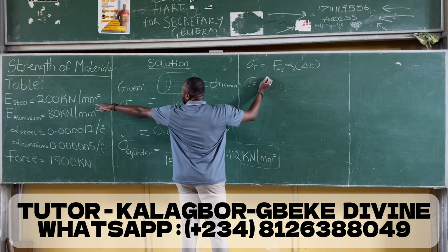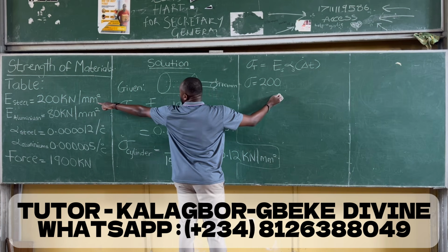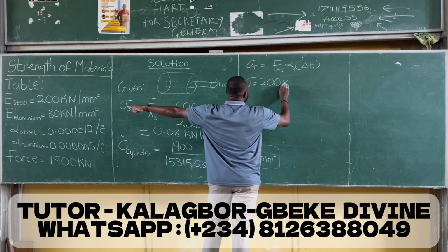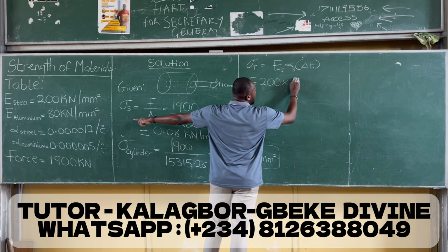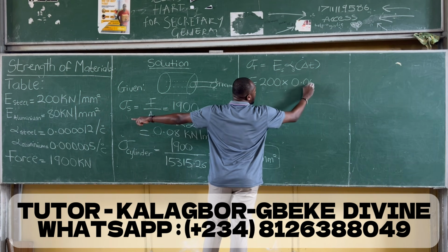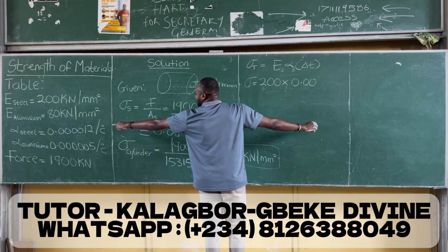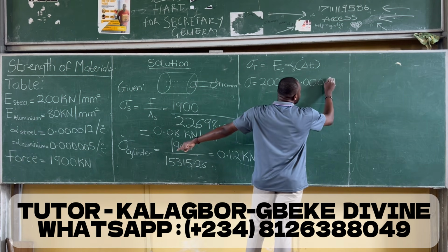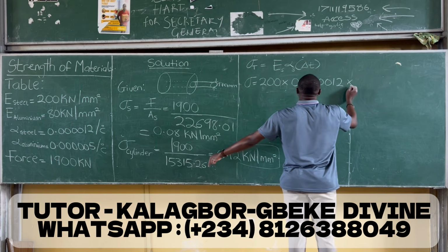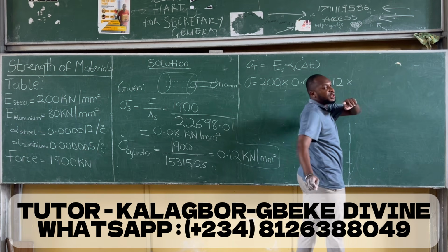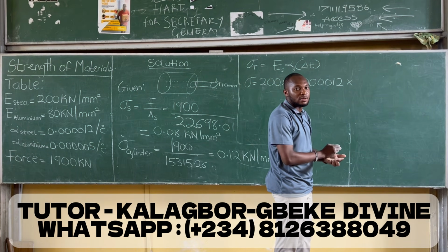Your modulus of steel is 200 kilonewton per millimeter square, times the linear expansivity of steel, 0.00001, times the temperature change they gave in the question, 120 degrees.